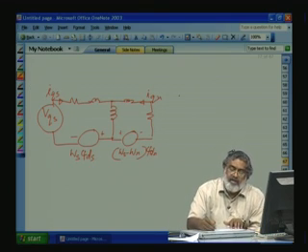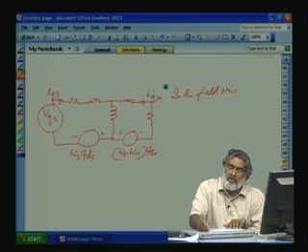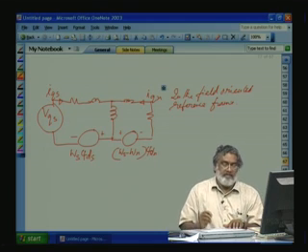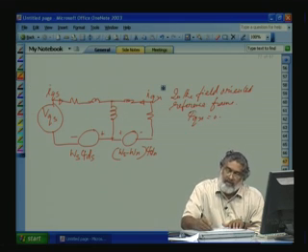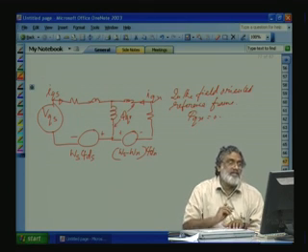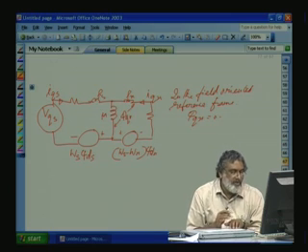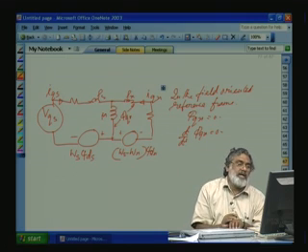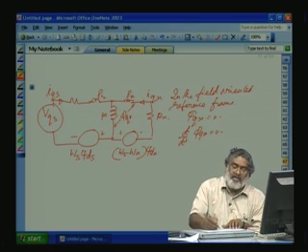Now psi QR is equal to 0 in the field oriented reference frame. Which is psi QR? Psi QR is the one due to these two fluxes. This is M, LR, LS. What this shows is that d by dt of psi QR is also 0. So the voltage coming across the resistance RR is equal to the rotational voltage, this one.